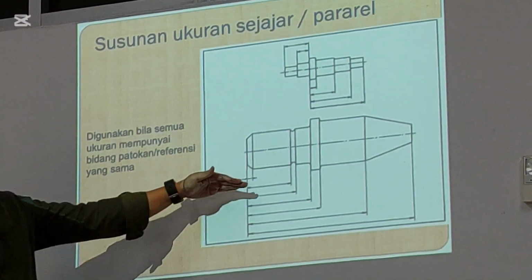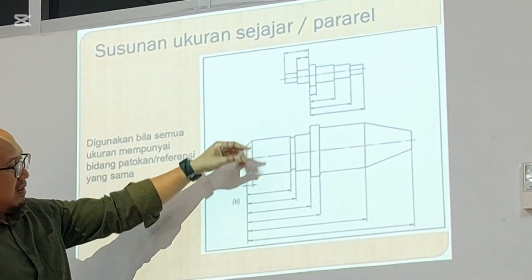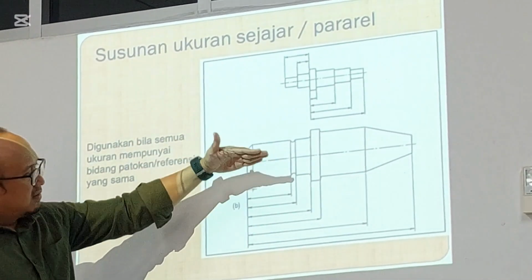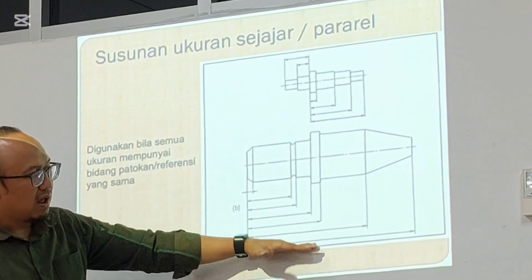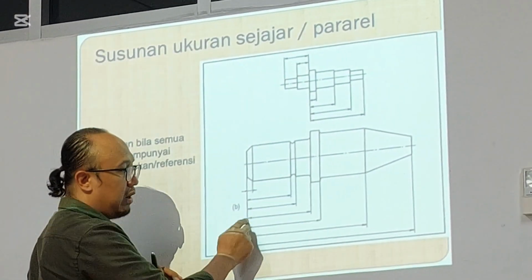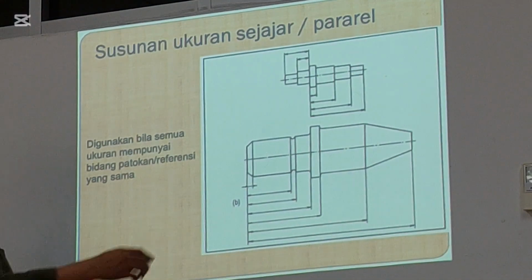Yeah, and also like this. Please arrange the dimensions in a good way: the smallest one, bigger, until the biggest one. So the lines will not cross each other. Also like this.